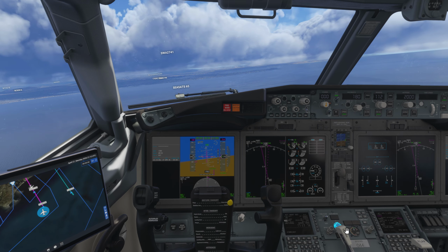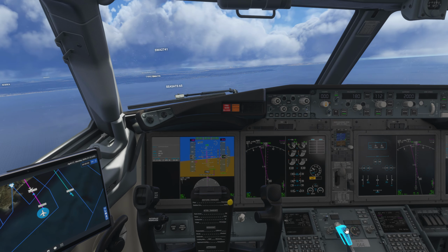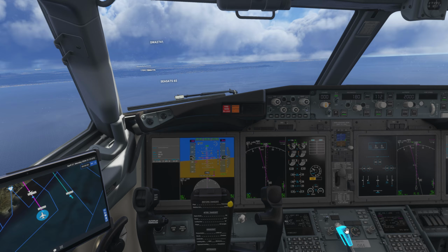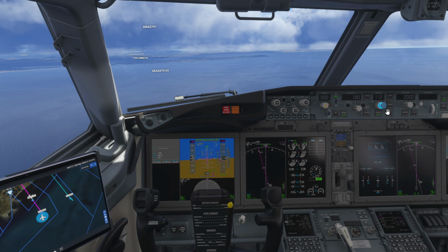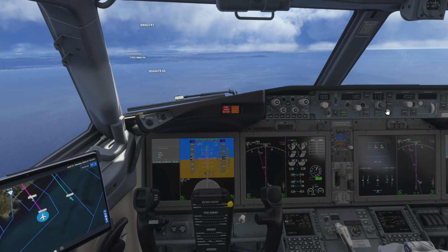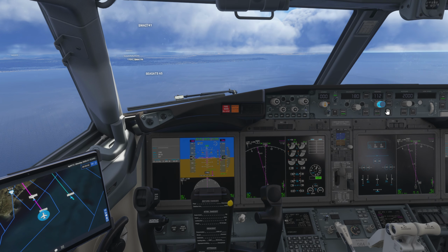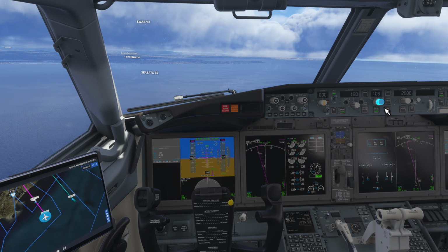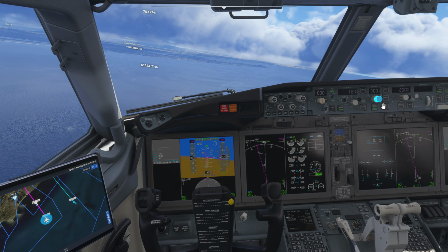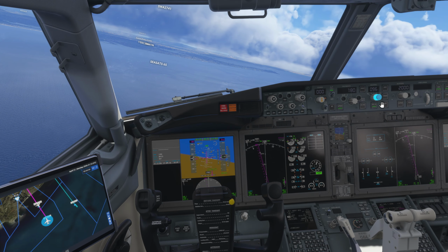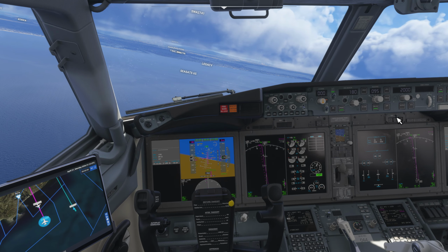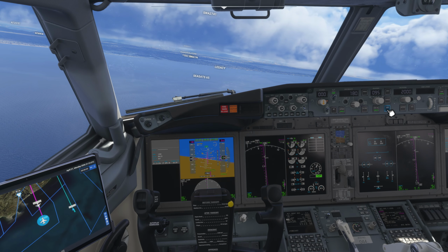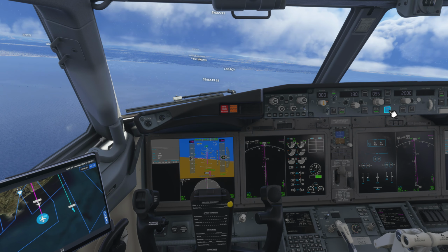Go to 30% on the flaps. Okay. And then put it back to 095. Go back to 095, the heading. And she's ready to activate the approach system. So let's hit that and hope that she talks to the airport.